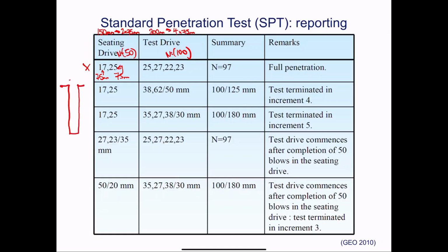Even if you have an auger and you drill down, you can even have flushing fluid as well. So the soil here, just at the base of your drill hole, can be highly disturbed. That's why we often do a seat drive to get our sampler just slightly past this highly remolded part. No matter what you do, it's highly remolded, okay? And the sample that you get is highly disturbed, but the seat drive is just an extra precaution.